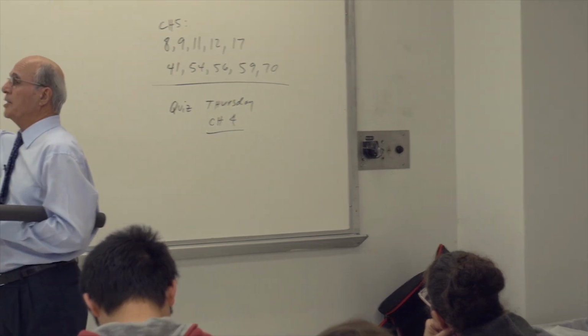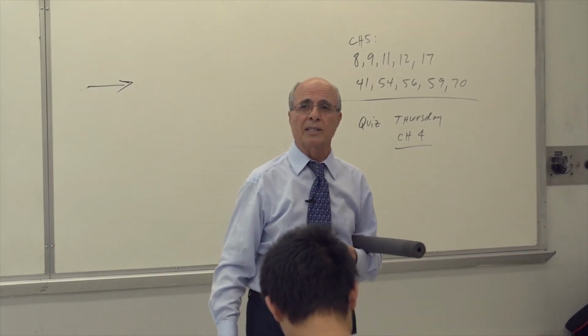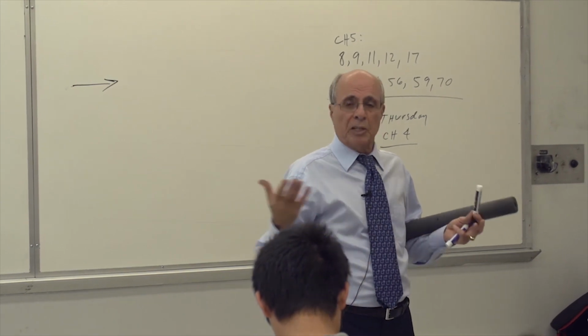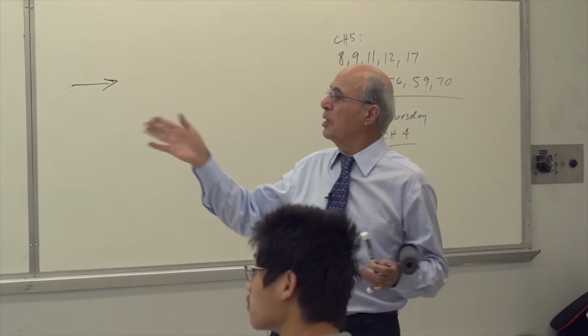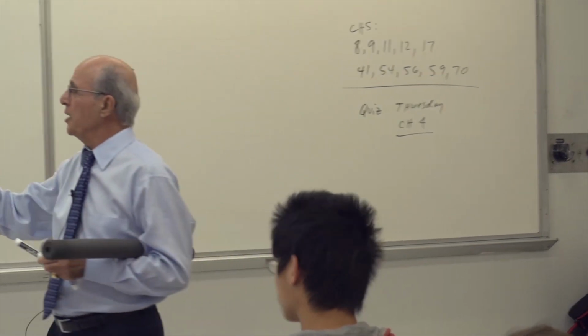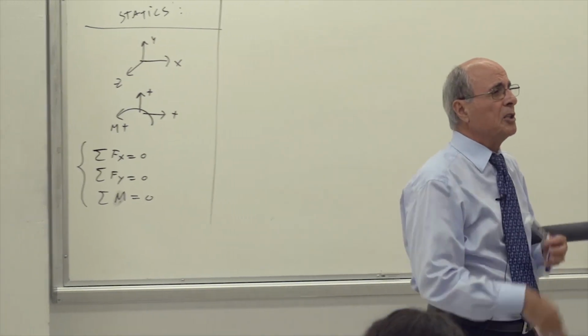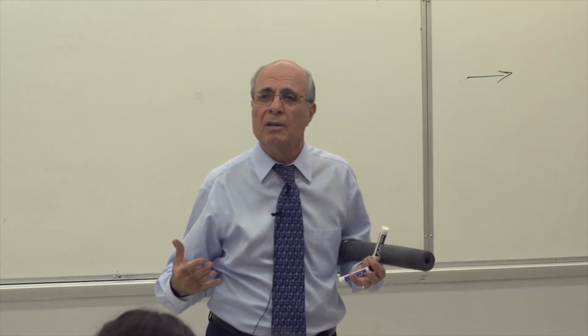This force statically is positive. Is it tension or compression? What would be your answer? Yeah, neither. That positive has nothing to do with the tension and compression. It is statically positive because it's going this way, and this is my axis. Is that correct? This is not either tension or compression.